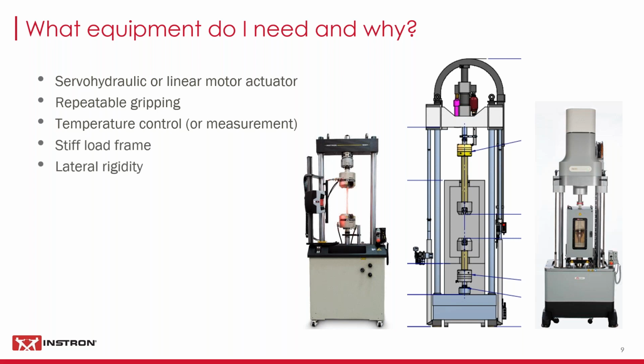Other general requirements, well, you've got to hold that actuator, and those grips have got to be hung on something. So you have a load frame, and you want that to be fairly stiff. You don't want it to wave around all over the place or experience compression during the test. But that's true of good quality metals fatigue as well.